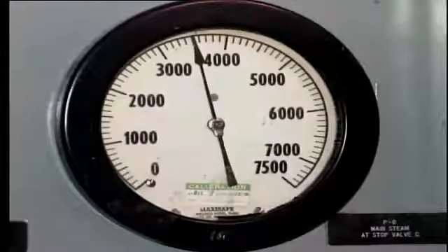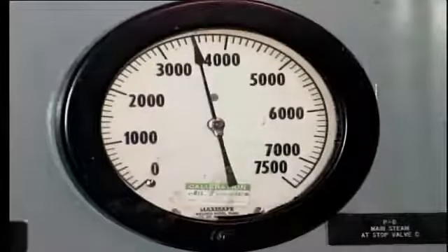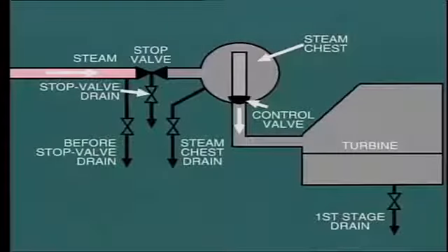It's evident that in most cases, we'll find the turning gear already in service with lube oil circulation. The generator hydrogen cooling system will also be ready for operation, and we'll be talking more about this in the next module. The next thing we must do is make sure that we have steam at the turbine stop valve and that the stop valve drains are open sufficiently to allow any condensed steam to be discharged from the pipework. We'll be discussing the procedure for charging steam lines in another module.